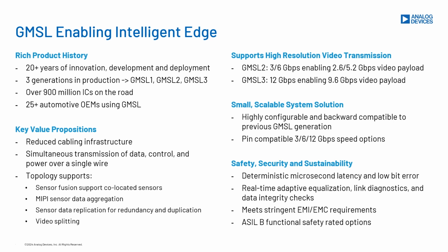For safety and security, the GMSL link has a deterministic latency in microseconds with very low bit error. The GMSL2 and 3 devices have real-time adaptive equalization to make sure the link works with changes in the environment. The GMSL SerDes also have many built-in features to support link diagnostics and data integrity checks, including for the video interface as well as the SerDes link.